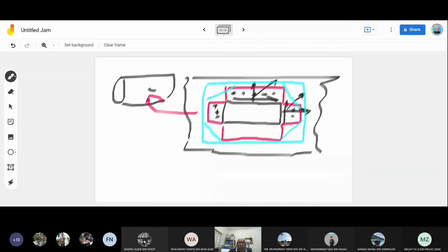Most of those losses are here, all the loss are here, and we install a doubler to recover the strength of the area, or to recover the loss. So basically we are just talking about this area, this and this area. So you put a big doubler, and you can easily just chamfer this one off, because this one does not affect the load carrying capability. It doesn't restore the strength for any of the plate outside this region.